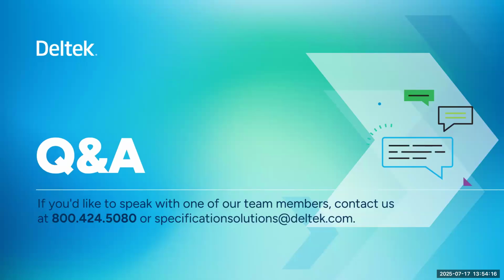Information submittals is basically just information that in the specs it may say we want to see a welding certificate, or we want to see a certificate from the installer that they have 5 years more experience. It might be something about a testing certificate or some information. And basically, you don't have to act on those. That information goes in your file. So if anything comes up later, you have that information to pull out as reference.